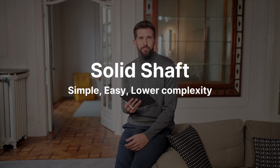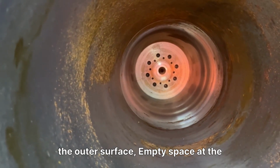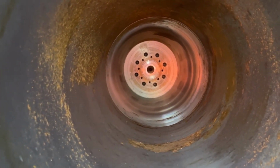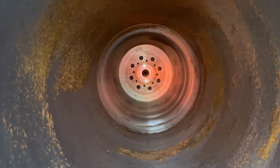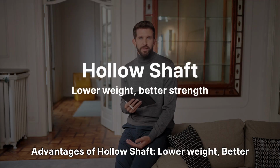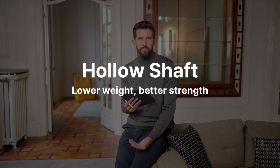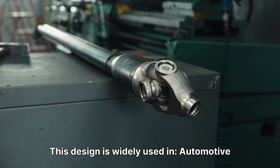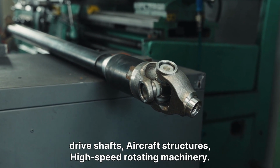Let's find out. A hollow shaft has material concentrated near the outer surface, empty space at the center. Sounds weaker? Actually, this is where engineering becomes interesting. Advantages of hollow shaft: lower weight, better strength-to-weight ratio, improved torsional efficiency, reduced inertia. This design is widely used in automotive drive shafts, aircraft structures, high-speed rotating machinery.